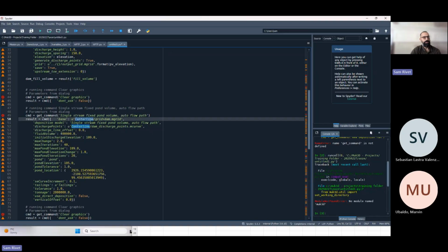And within that centerline folder, named after my dam template, there's always going to be this grid plus dam surface. And that's always going to be valid. I always want to pour tailings on a grid plus dam surface. And the grid plus dam surface in every iteration is going to be my output grid from the previous iteration with that new lift on. And that's always where I'm going to want to pour tailings.